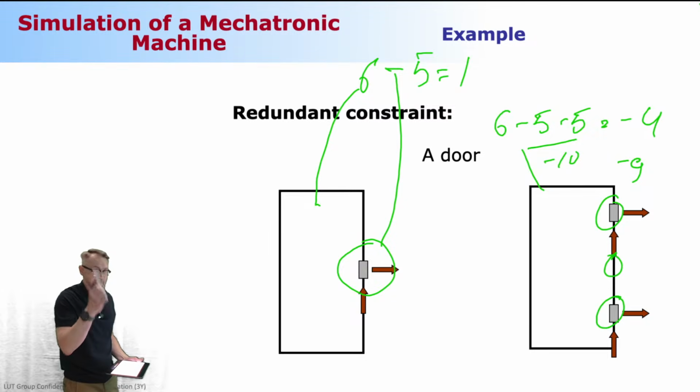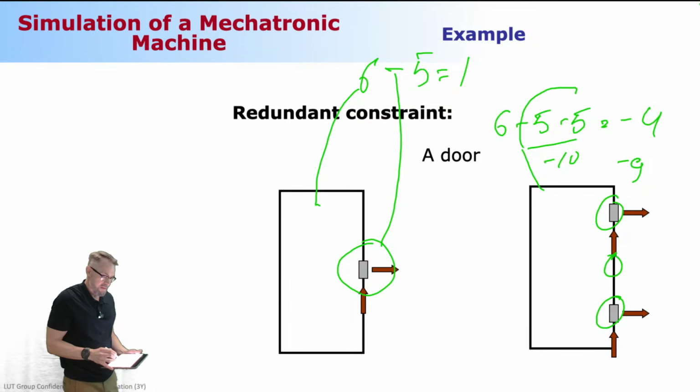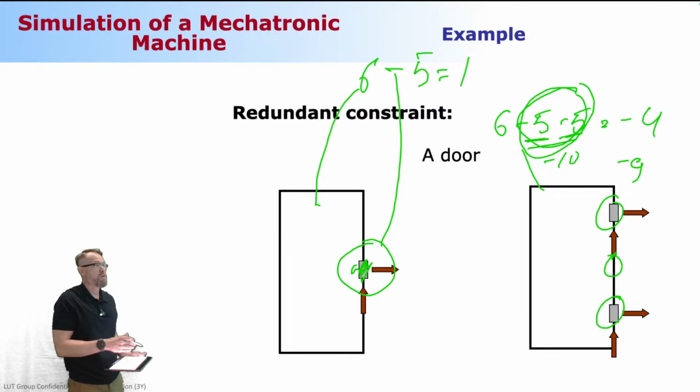Explanation is this. The constraints only take degrees of freedom away if the constraints are independent. What these 2 guys are doing, they're constraining exactly same generalized coordinates. So these guys are not independent, but they are dependent. It's the same as if I'm going to set 10 revolute joints in this same location. They are not constraining different kinds of motion, but the same motion over and over and over again. And because of that, they are not independent. This is a redundant constraint.